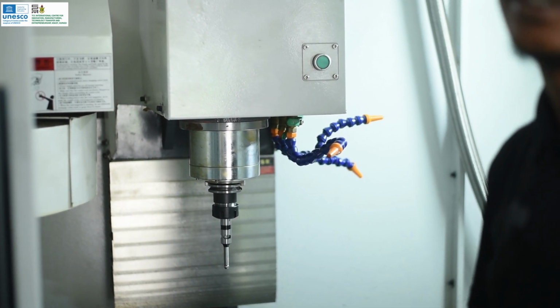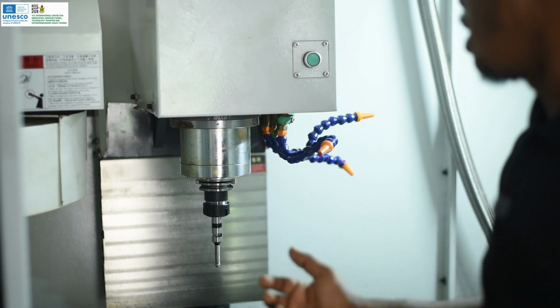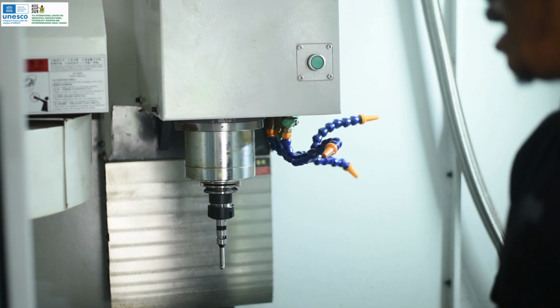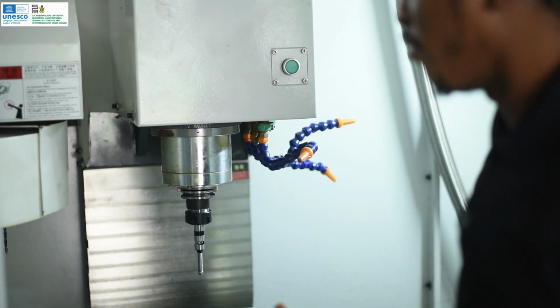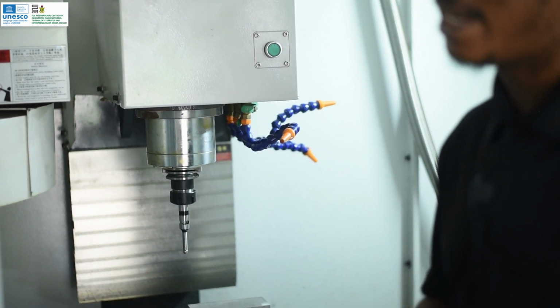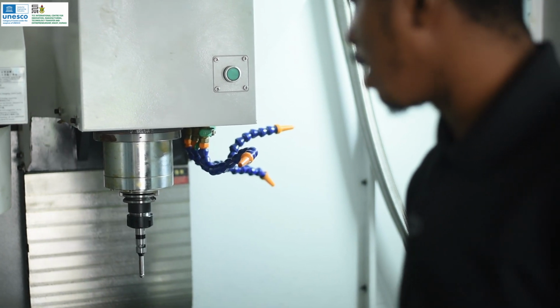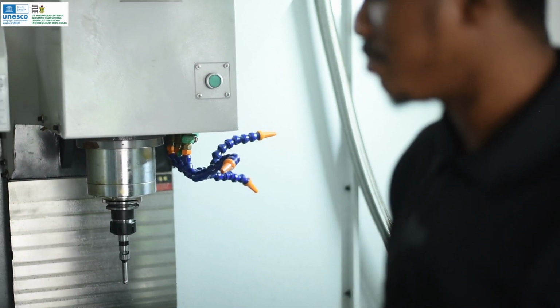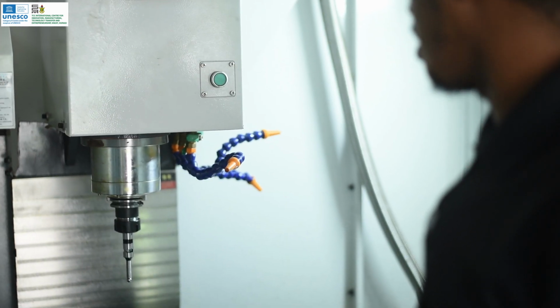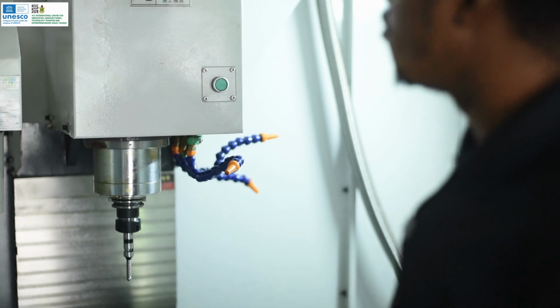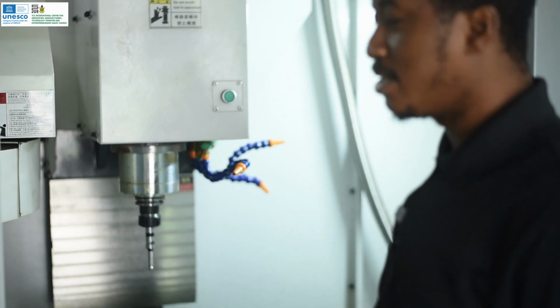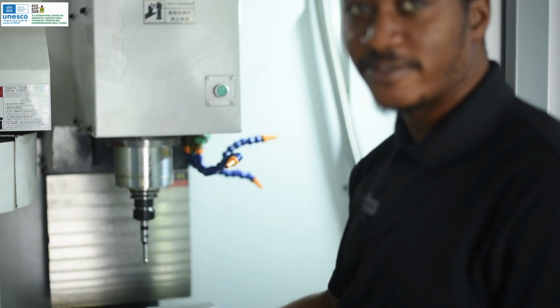Okay, hence the 5. Now let's explain why in some cases we're using a -5, and for example, in the X, we're using a -5, and then in the Y, we're using a +5. Now, the CNC machine has a coordinate system, so there are movements that are in the negative direction, and then movements in the positive direction.